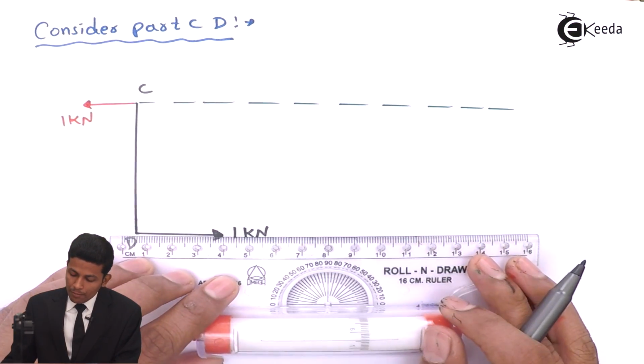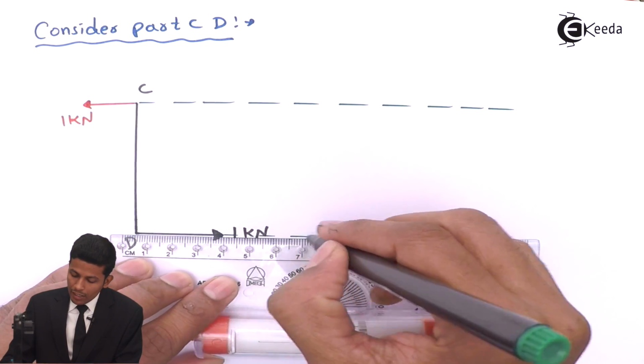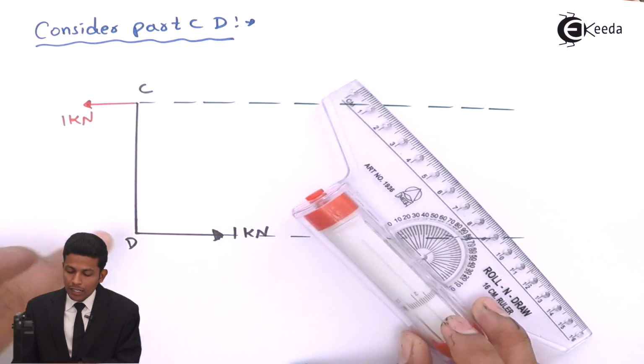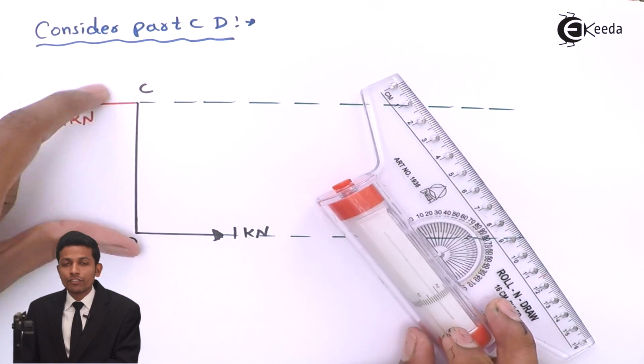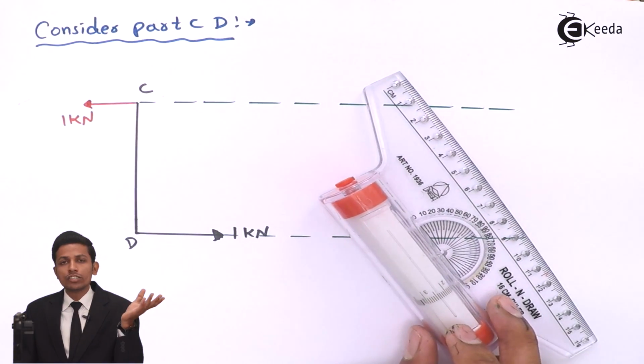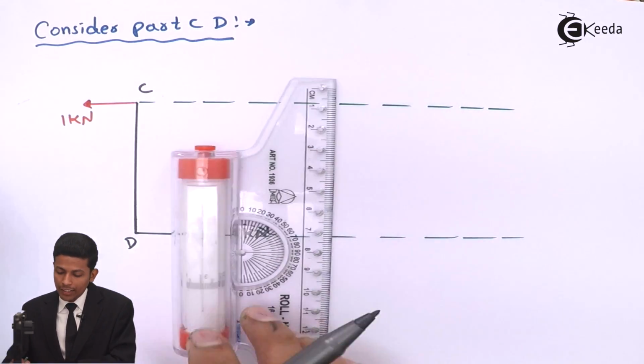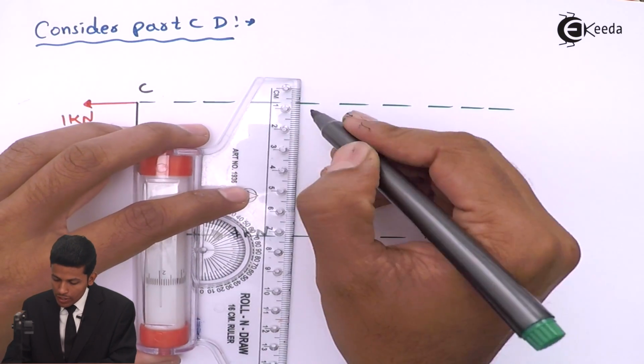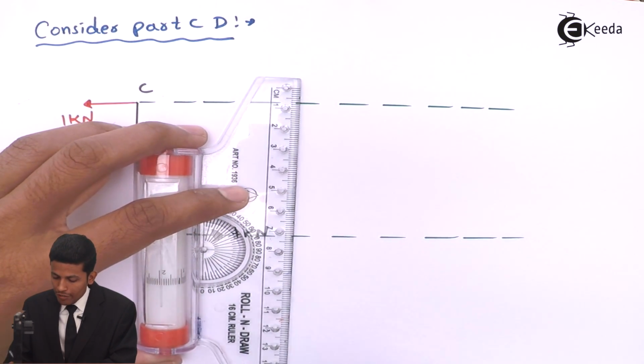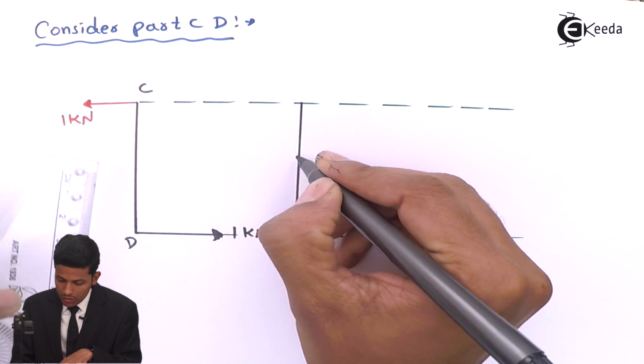No need to, I am repeating again and again, please do not consider the couple in this beam, because it will get complicated for you. Directly see the original diagram and draw it, and this will be correct. Okay. Now since there is no axial force diagram, therefore its AFD will be 0.